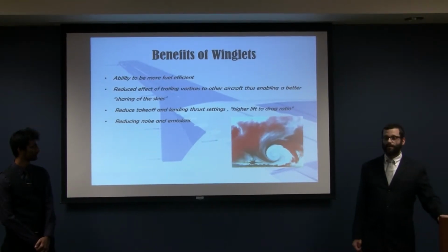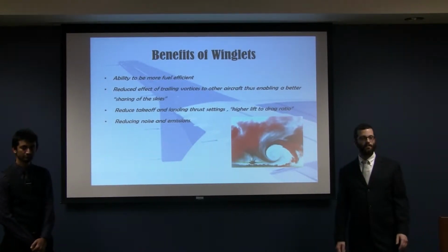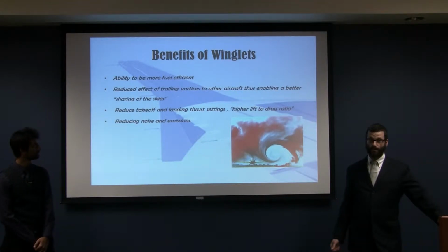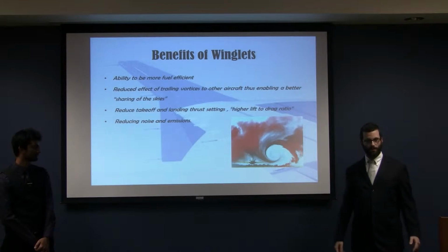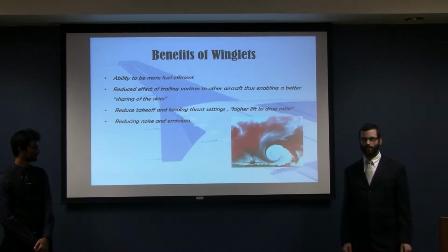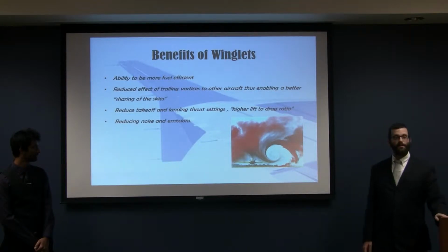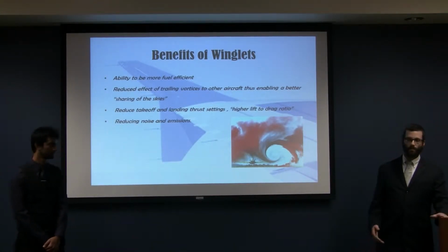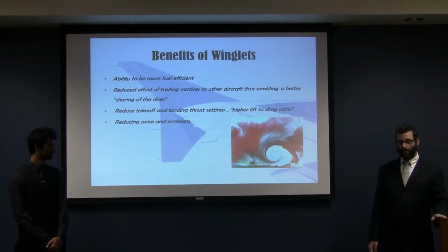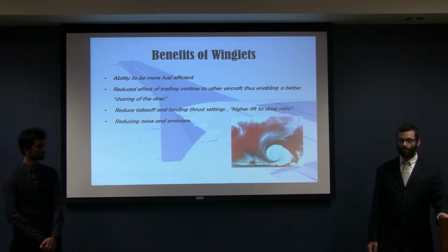The benefits of winglets are, overall, lower fuel use and more fuel efficiency. Another added benefit would be that aircraft trailing in the wake of this aircraft experience less turbulence in that region, since there's less vortex effect. Another benefit would be that since the engines are operated at lower settings, you have less fuel and carbon emissions, you have less noise pollution, and another benefit would be that you can achieve takeoff velocity in a shorter amount of time.